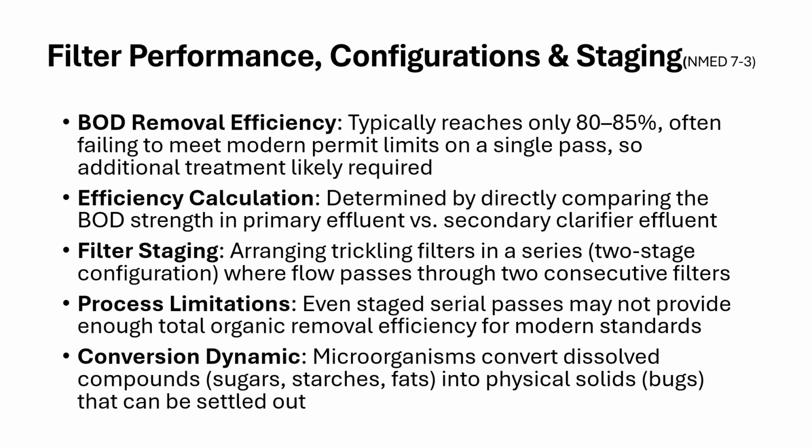So that's the interesting part. All we're doing here is converting one source of organics, the sugars, starches, and fats, into the microbial mass or the slime layer, letting it fall off and then letting it settle out as a solid in another clarifier. Pretty slick when you think about it. We're letting natural processes do a lot of this for us, and it's saving us a lot of money and time, and it's fairly efficient when you think about it.